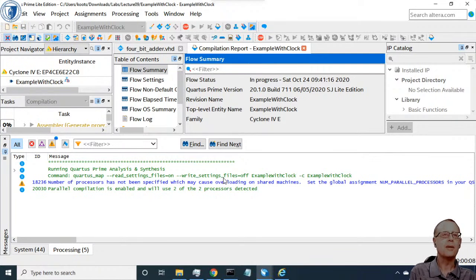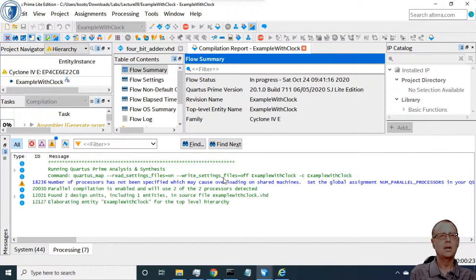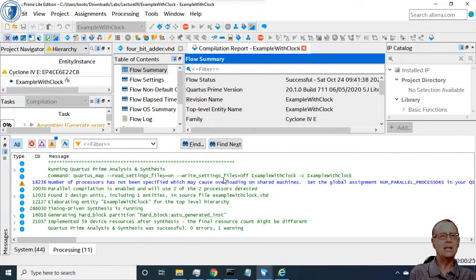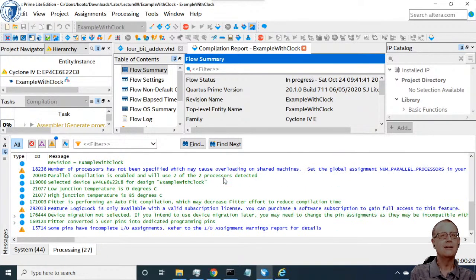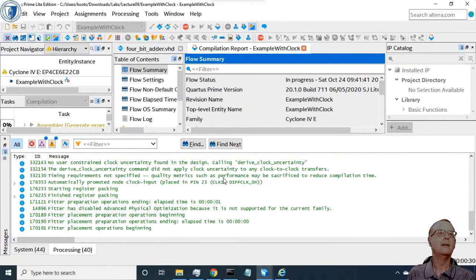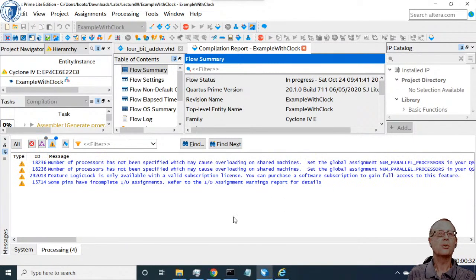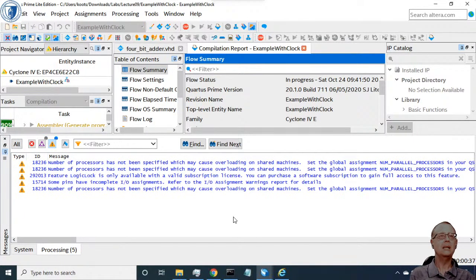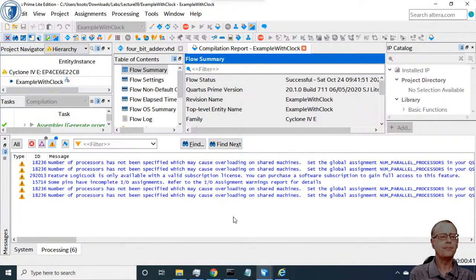It might be because of other changes I've made. So the two warnings that I got, one of them was complaining that count and divided clock were being read in the process but were not part of the sensitivity list. So I put them in the sensitivity list to remove the warning.